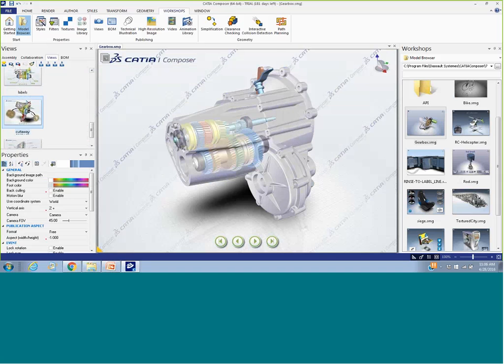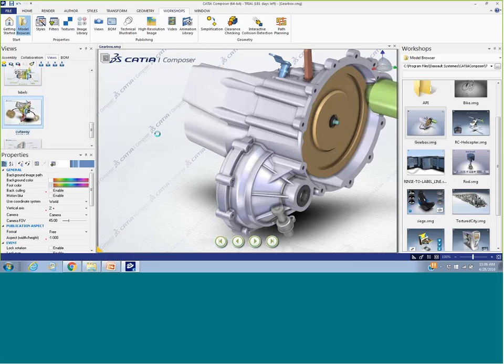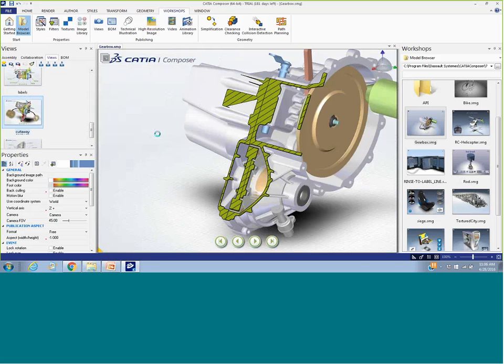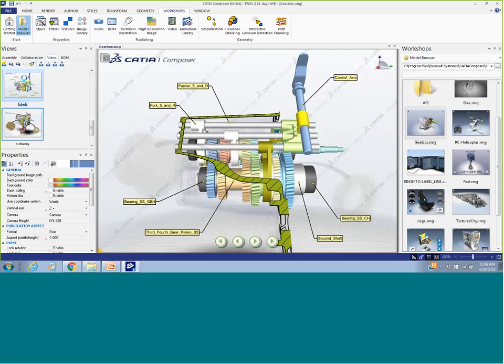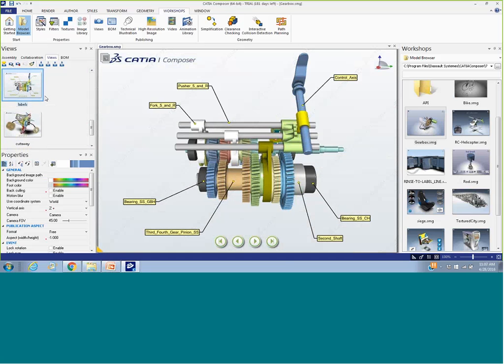So again, you can then go through and set different properties, based upon what you want to see. You can even have cross sections like you see. Again, you can have dimensions easily created inside. You just need to double click on the view. It will take you there. And then if you do have some type of bill of material that goes along with that item, on this bill of material page, you would list the bill of material that goes along.